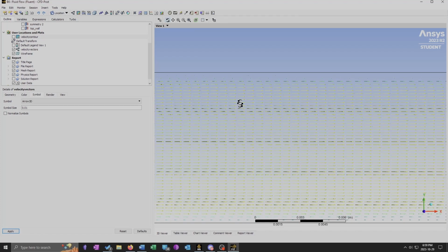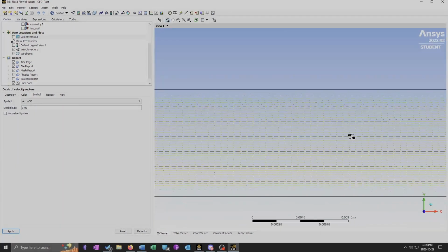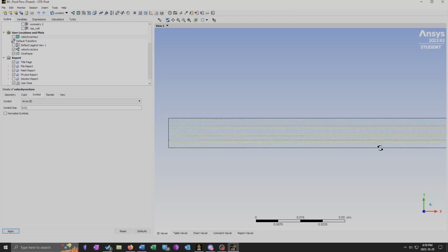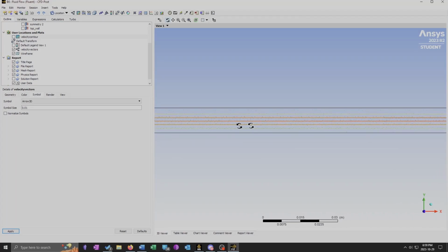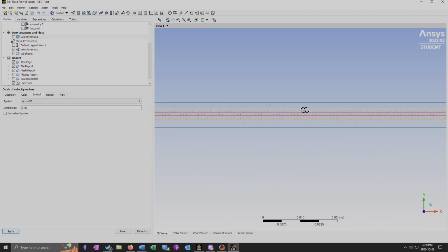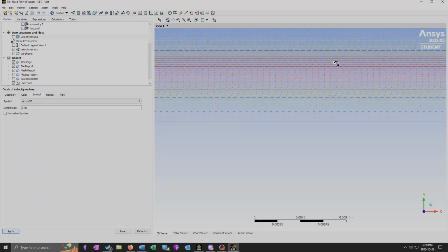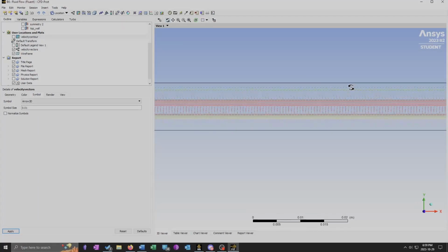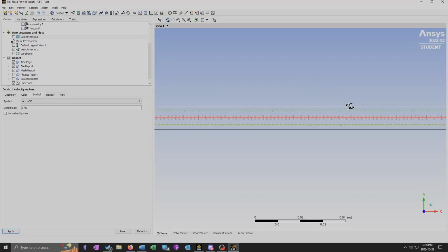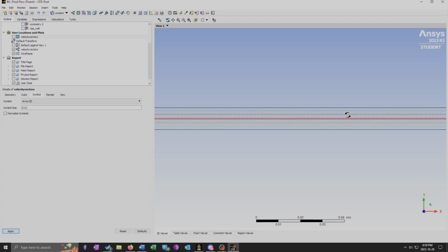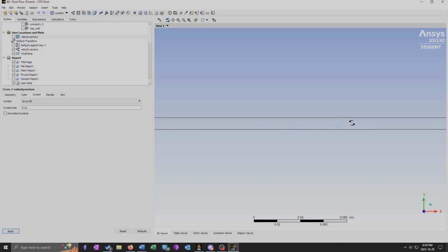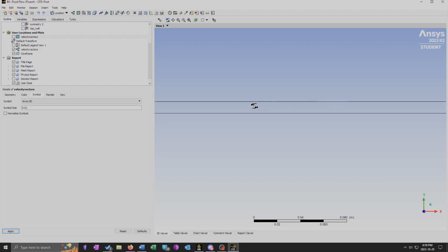So you can tell that the velocity gradient isn't that significant at the beginning. But as you go on, it gets much more significant because the center becomes very high speed, and the outer parts that are away from the center are lower speed. This is what we expect because of the no slip condition. There is no shear at the center. That's because it reaches the maximum velocity.